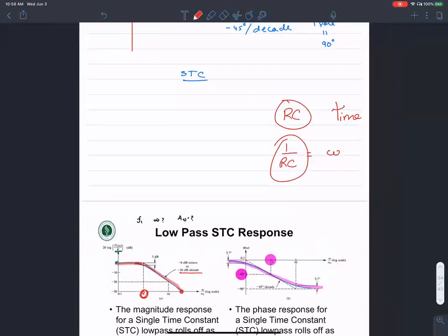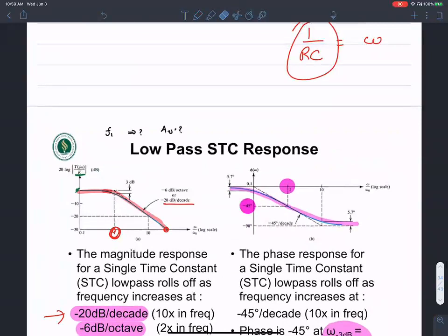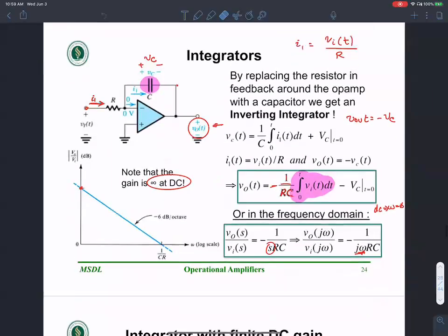If you plot the frequency response, just like you did in the first lab, you will see that the gain at DC, if it was 100 dB, let's say, at the pole frequency will be 97 dB, 3 dB below. If you go to 10 times the pole frequency, it's going to be 77 dB. You can verify this using your frequency analysis, and you'll see that for one decade change in frequency, a 10x increase in frequency, the gain will come down by 20 dB. So that's the idea, and this is simply an expression of the frequency response of the amplifier.